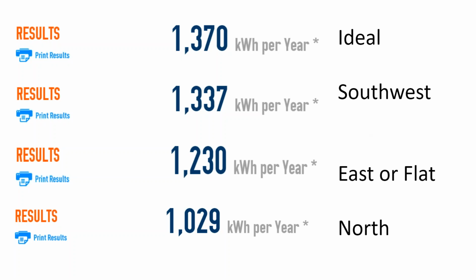Because if you're already filling up 3/4 of the roof with solar, doing the last quarter doesn't cost a direct ratio. You start getting into economies of scale where buying a few more panels, moving on to the next roof surface, now that you've already overcome the site mobilization costs, making the array a little bit larger, even though that section might be a little bit less productive, can sometimes improve the project economics.